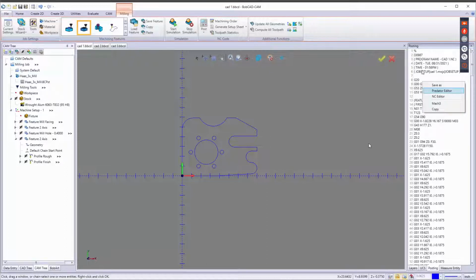Don't save this G code directly onto your desktop. You can save it in a folder that's on your desktop. That's fine. There are read-write issues on there. If you save it directly to your desktop, it will corrupt that G code file, so it will just error out on your machine or won't open at all, won't recognize it.